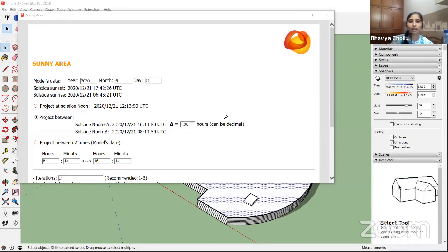But for time you can understand it this way. As you all know, solar generation is not throughout the day. It is only whenever the sun is present. In that case, we will not consider the complete shadow region on the location. You take a certain time window where the shadows can be considered, based on your time duration in SketchUp for the analysis.